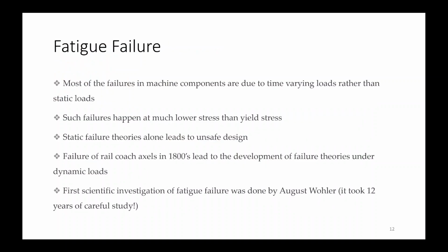Now we'll be going through some lecture notes. So firstly, what is fatigue failure? Most of the failures in machine components are due to time varying loads rather than static loads. In case of static loads, if you are applying for example a 10 MPa load, then it will be constant throughout the time. It won't be changing with time. While if it's changing, then it will be counted in fatigue failure.